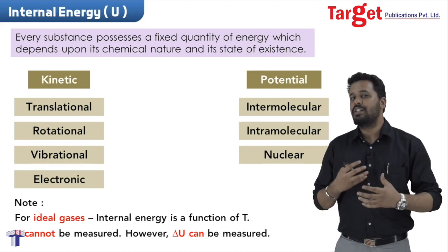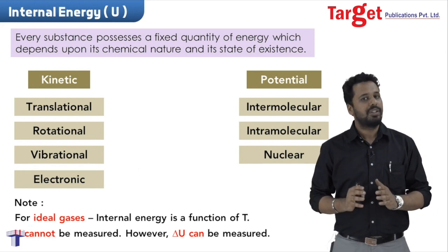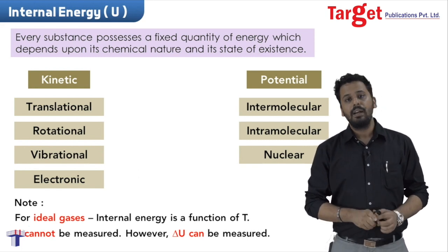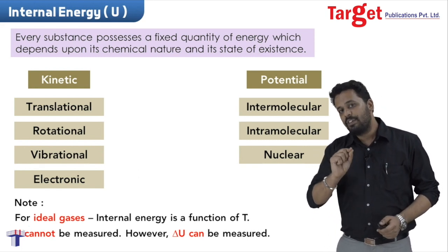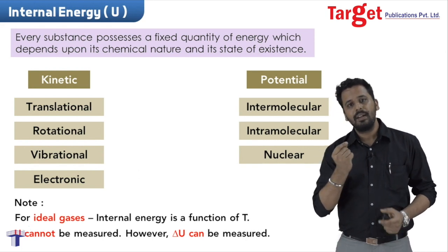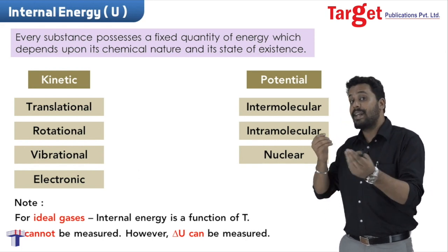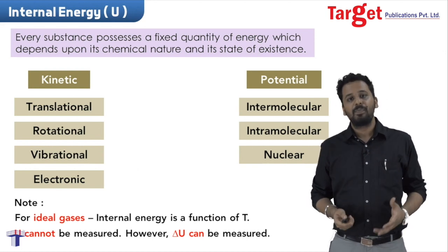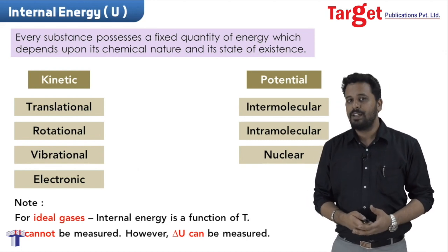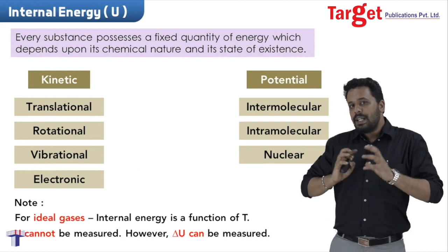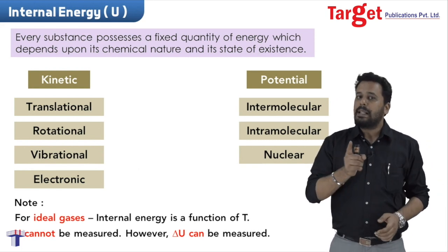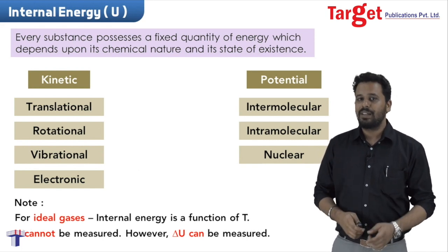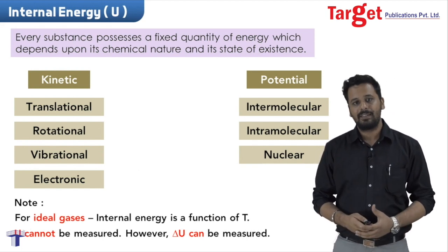हम internal energy यानी कि U directly measure नहीं कर सकते, because internal energy measure करने के लिए हमें हर एक molecule का vibration, rotation and उसका motion, वो भी किस direction में है, ये सारी चीजें हमको पता करनी होंगी, and currently we do not have sufficient technology to find that out. So internal energy हम find out नहीं कर सकते, लेकिन change in internal energy हम find out कर सकते हैं by using the first law of thermodynamics.